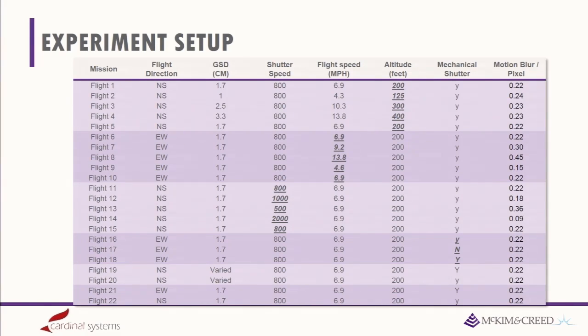So photogrammetry really kind of boils down to two things. You got your EO and your IO. This is your internal orientation, your external orientation. So basically, where's your image in space and what's its orientation, and what's the internal parameters? What's the mathematical model for the distortion of the camera? But all these different variables in a camera are going to affect that. Your flight speed is going to introduce motion blur. Your altitude is going to lower your ground sampling distance.